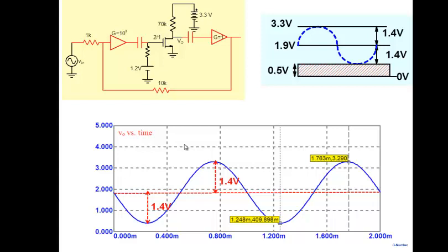Now what happens is, when I said I take a common source amplifier as a standalone amplifier, I have to worry about its harmonic distortion. But when I take the same amplifier, embed it in a larger amplifier and use negative feedback, it is getting rid of harmonic distortion. And therefore, harmonic distortion is no longer an issue.